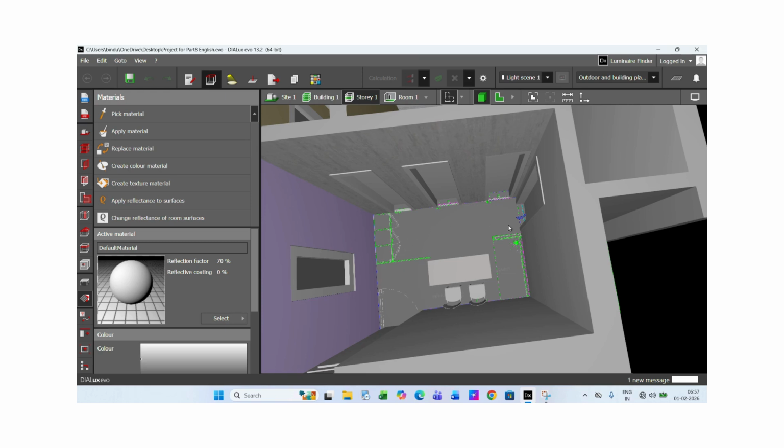Otherwise, in an operation theater you need the light to be concentrated on the surgical table. The surgical table has a task light, which is different from the average illumination for the theater. When you are calculating the lux level for the surgical light, the lux will be in terms of thousands, like 10,000 or 15,000 lux.